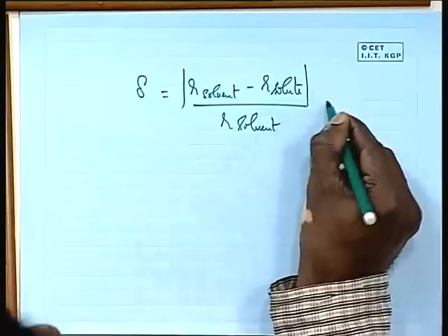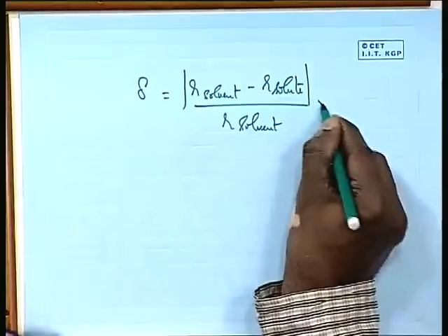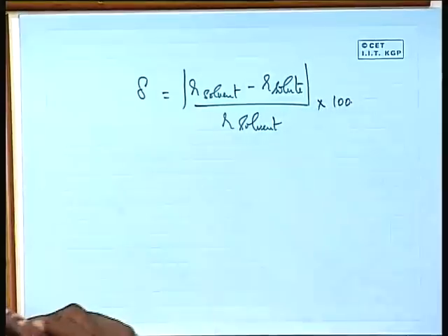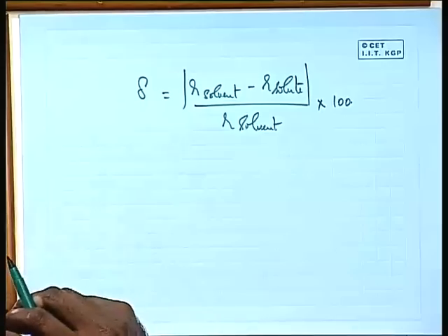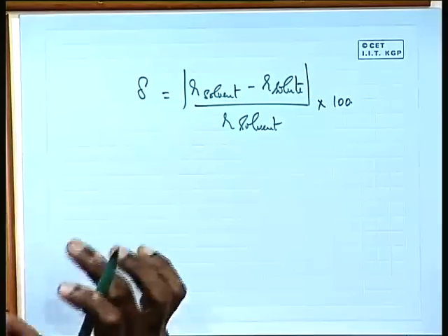So this is always expressed in terms of percentage. Multiply it by 100, you will get a percentage, and that is what we call the size factor delta. If it is much smaller, we get a solid solution. And if the size factor is larger than about 12% or 15%, which again is a thumb rule, an empirical rule, people have found that one can easily get a glass.